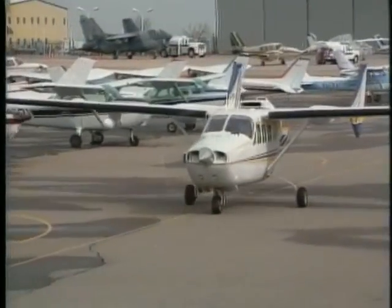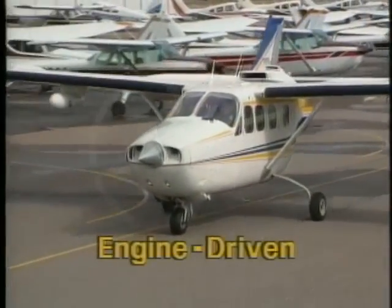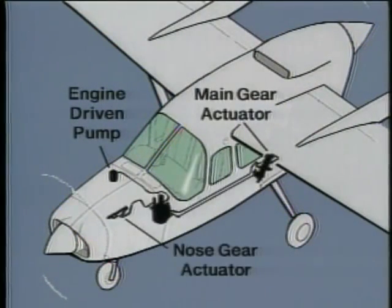The next system we'll look at is the hydraulic landing gear system, which uses an engine-driven pump. In most cases, the pump is located on the accessory section of the engine and uses a series of valves, pipes, and hydraulic actuating cylinders to transfer the hydraulic fluid necessary to raise and lower the gear.